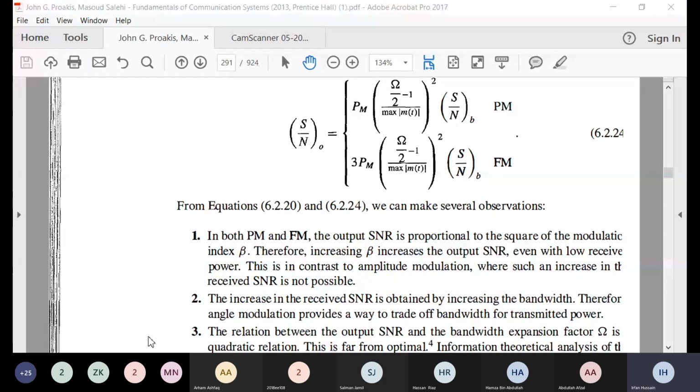But for example, if I shift my triangle to some higher frequency, then remember that the triangle's bandwidth will be actually double as represented with respect to its mathematical representation. That is the difference between a rect and a triangle. That is very important for our understanding of communication systems. Because of convolution the bandwidth becomes double, and that is the reason.